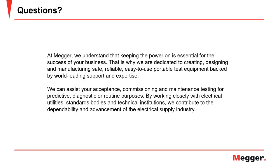All right. Thanks a lot. Next is over to Sugosh. Sugosh, with regards to motor differential protection, do you compensate for any CT lead length differences to the protective relay, or is this compensated by a small slope value?